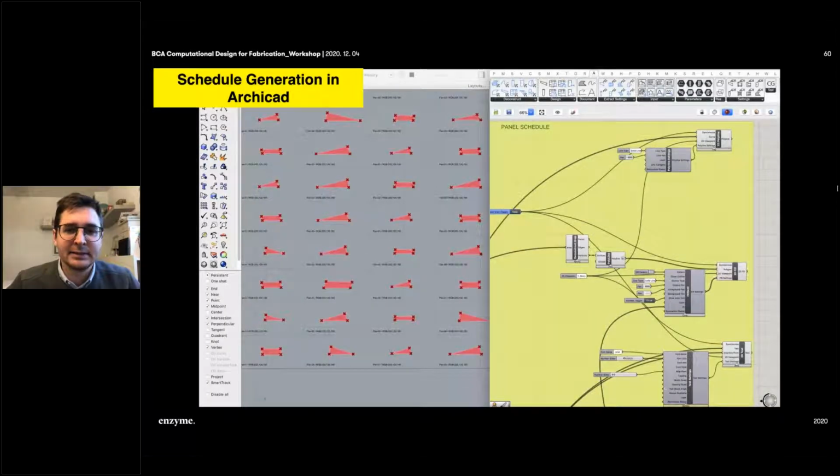At the end, what we want to do as well is have this schedule in ArchiCAD. Since the object was not ready for scheduling yet, which will make it really easy, what we did is a strategy, a small workaround, and then we use all the projected elements with their ID in the Grasshopper screen. We just send them to ArchiCAD by creating the schedule itself from Grasshopper.